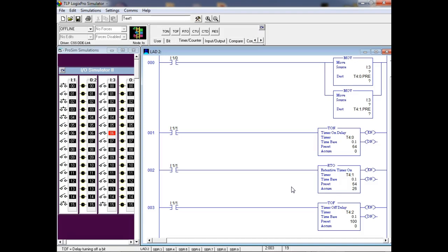We have Boolean algebra for what? Well, control. Yeah. So anything inside this over here, we can represent as a Boolean algebra expression. Anything over here, the outputs, are not Boolean algebra. So what you're doing with Boolean algebra, you're trying to reduce the amount of devices that's required to make a rung true, right? That makes sense?